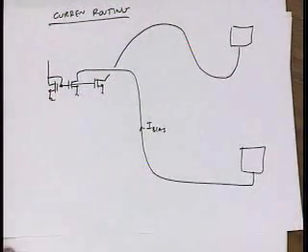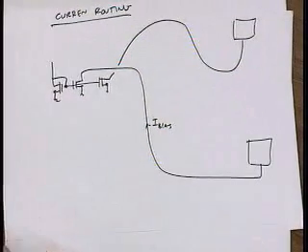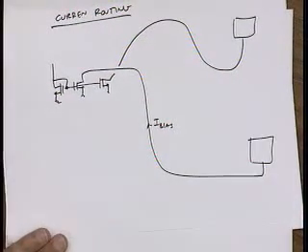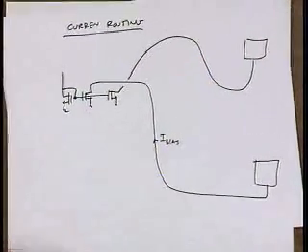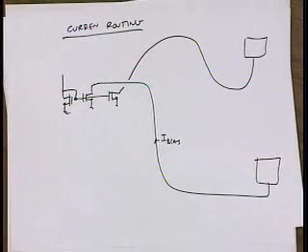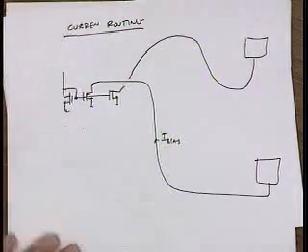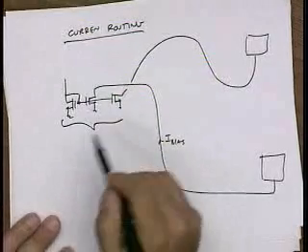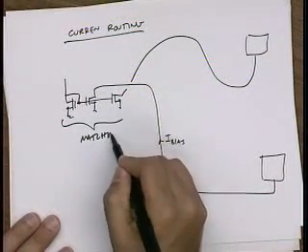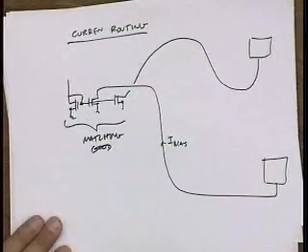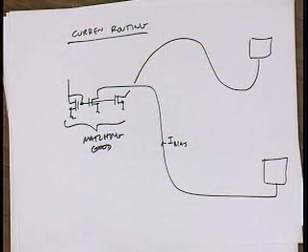Okay. Any comments about this approach? Benefits, or first of all, one benefit is that you're now not sensitive to matching because you're taking advantage of the fact that the transistors are close by. Okay. What are some disadvantages of this approach?